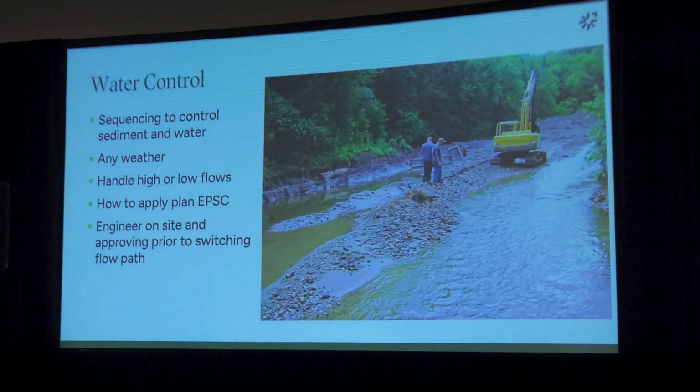And so, when you're moving into construction and you're making your observation visits, reviewing the water control is really crucial. We want to make sure that they're prepared for any weather, that they're sequencing, removing sediment, controlling the water, whether it needs to be moved around, make sure that there aren't major discharges from the site.